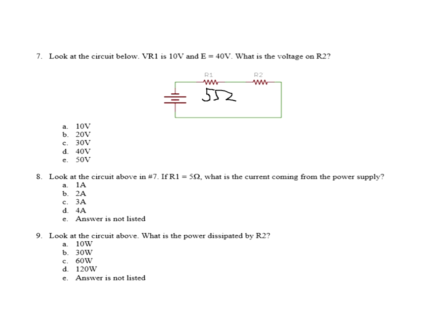All right, what else do I know about R1? Well, I know that R1 has 10 volts on it. Now this question will take a couple of different forms. They might say, what is the current coming from the power supply? Or they might say, what is the current in R2? Well, we know that the current is the same in the series circuit. So if I find the current here, I know the current here or there.